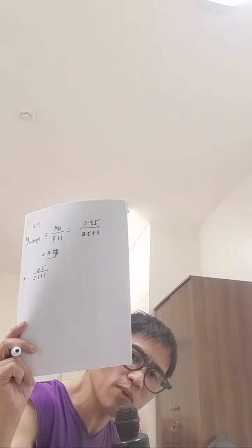Okay, so the slope is equal to the reflux, how much is it? It's mentioned in the problem. 2.5 over 2.5 plus 1. This is coming from R over R plus 1. So now our slope will be 2.5 divided by 3.5, which is equal to 0.71, the slope.